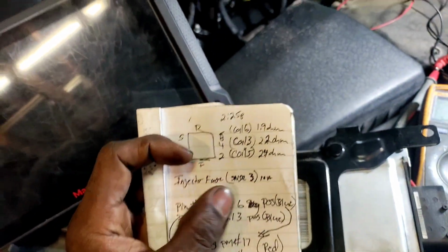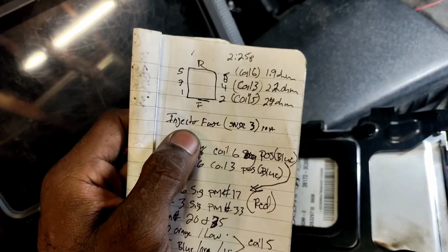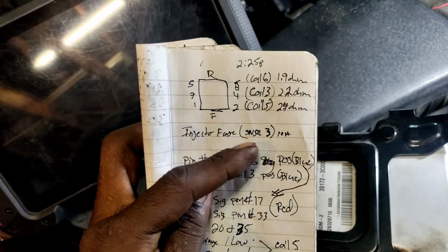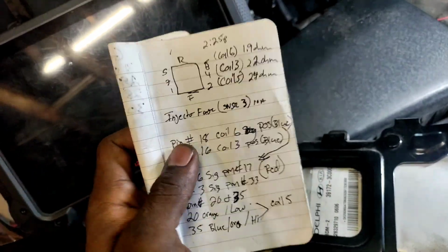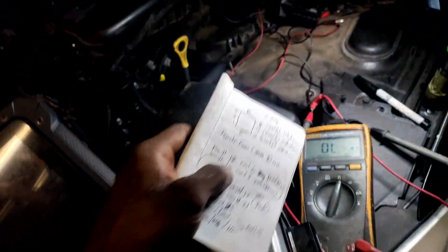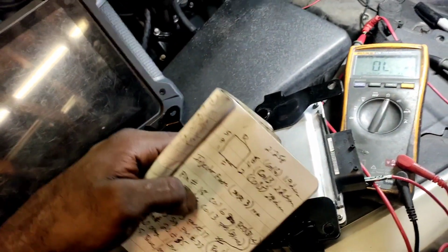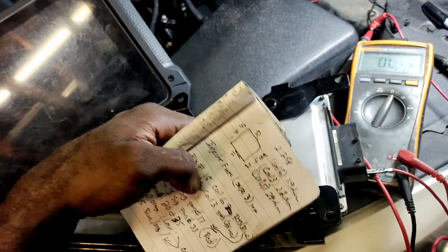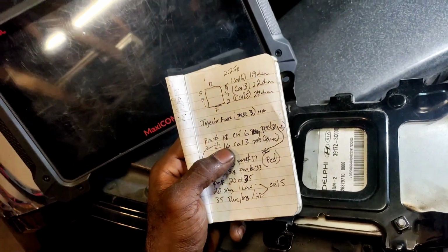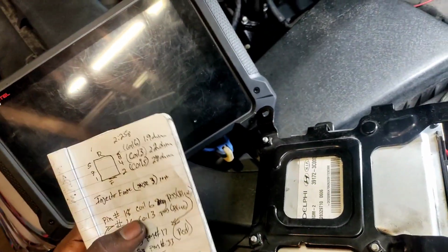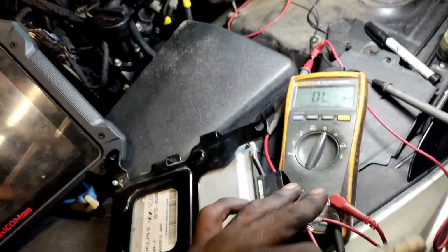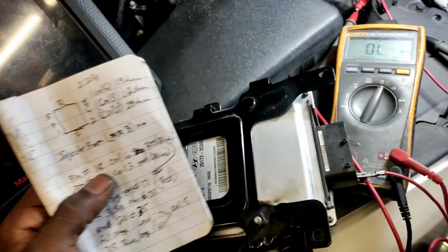Usually when I get desperate, I'll start checking resistance. That's me checking the injector fuse here. I was trying to link up with that on the amp clamp, but that did not work in the fuse box, because this system uses an injector control module to individually supply power to the isolated injectors. So it's not like a batch fire or anything, as I understand it. These pins come out here, two pins go to each injector, and it does that for all six of them.